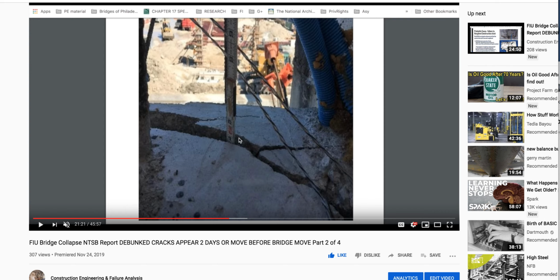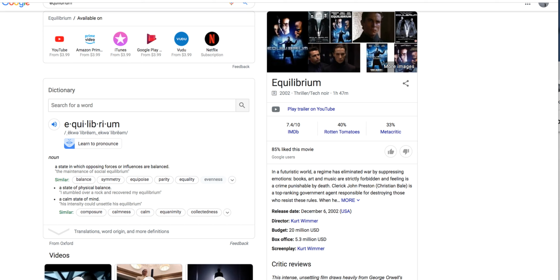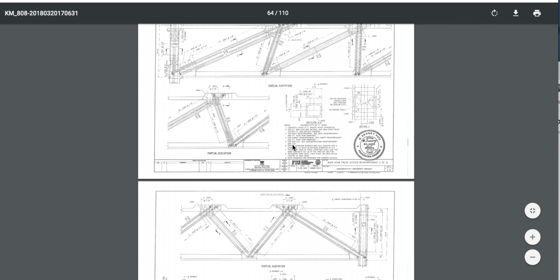This is simply a tied arch bridge system that Denny Pate created by accident, because that wasn't his intent. When he released the end connections on each end, this allowed the bridge to sag further. Of course, being tied in with the truss members the way they are, it was able to pull down, pull up, pull down, pull up. It went down. This sagged down.